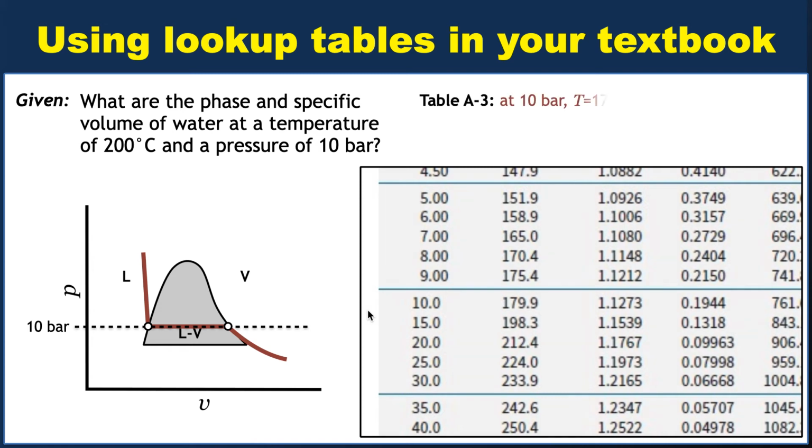Well, we can put that up here. So at 10 bar, we know the temperature. We've just essentially looked up the isotherm that we already drew. And remember, that corresponds to the temperature right there. It's inside the vapor dome for this table. So if that's the case, we can label this isotherm 179.9 degrees C,